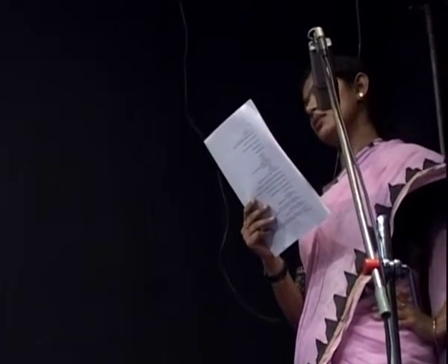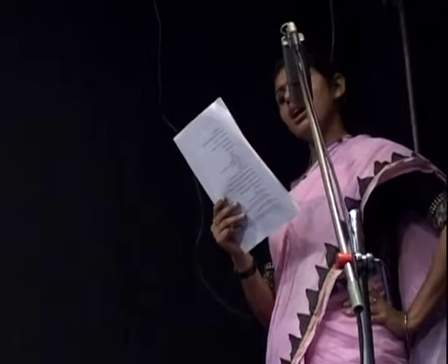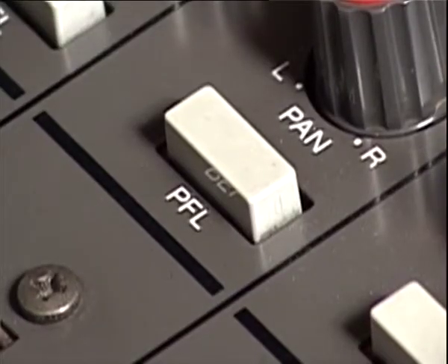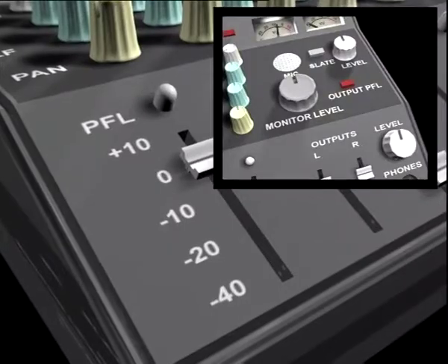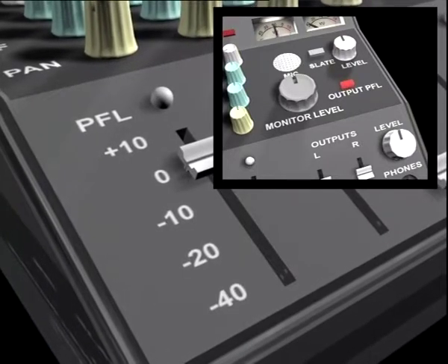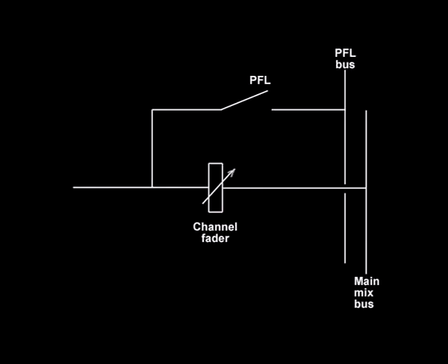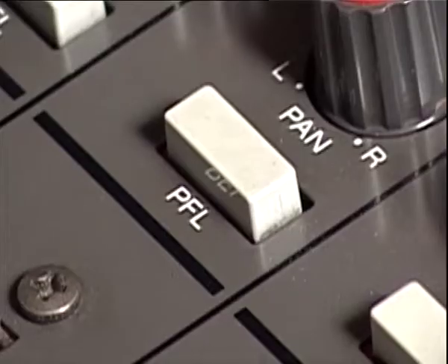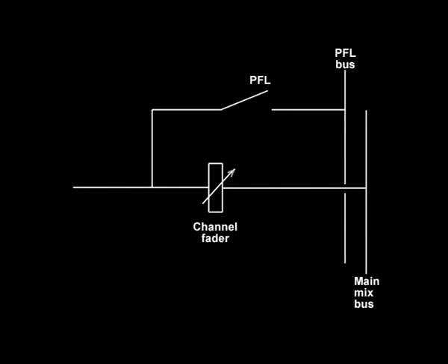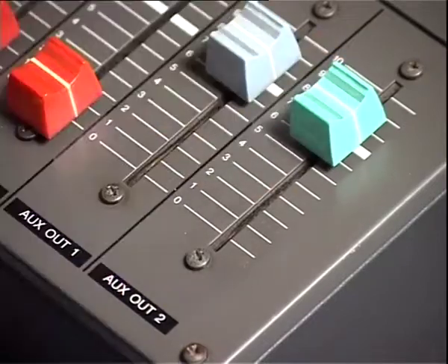Adding a simple reverb to our mic in signal will make it sound warmer. Before sending this processed signal to the output, we may like to listen to what it sounds like. On pressing the pre-fade listen button, the signal is routed to the monitor. Once we are satisfied with the outcome, we release the PFL button and send the signal to the output via the fader.